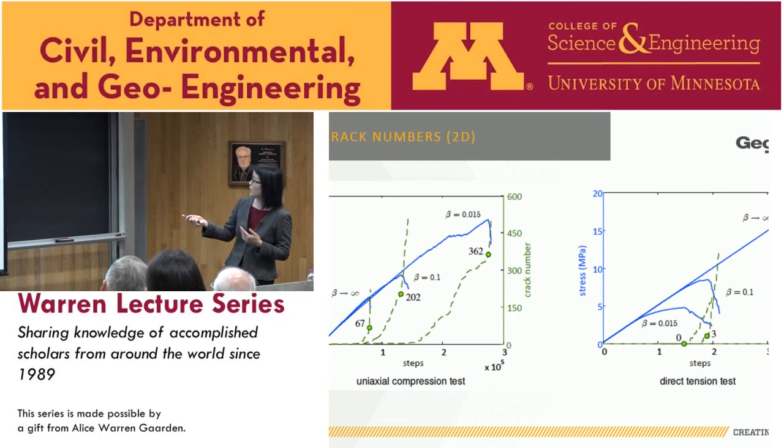If you look at the peak in uniaxial tension, there are barely any micro cracks at the peak. So the peak at uniaxial tension is actually at the moment when the system hasn't really cracked. There are only a few tiny ones, and then after that, the through crack would be developed afterwards in the post-peak area.